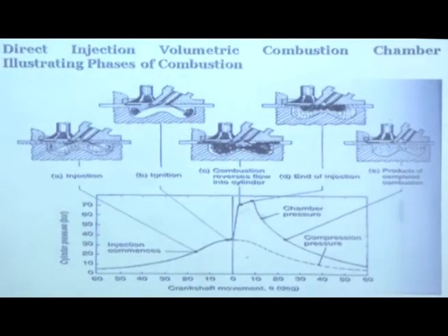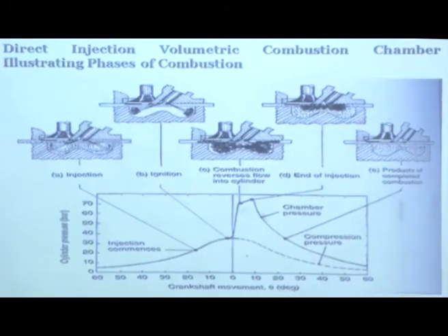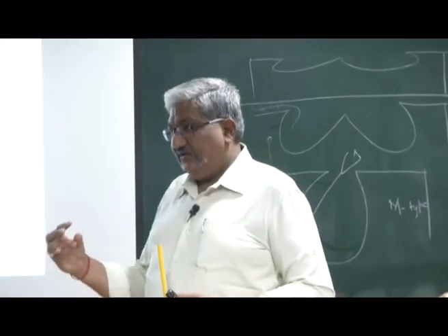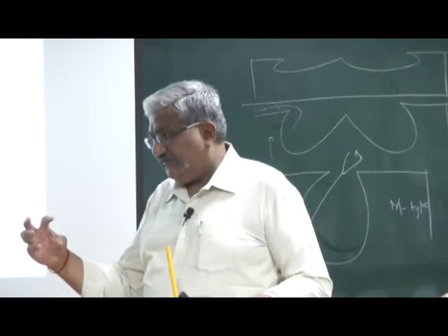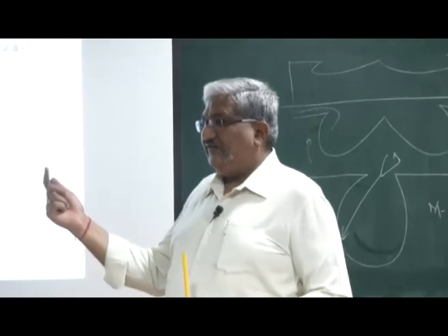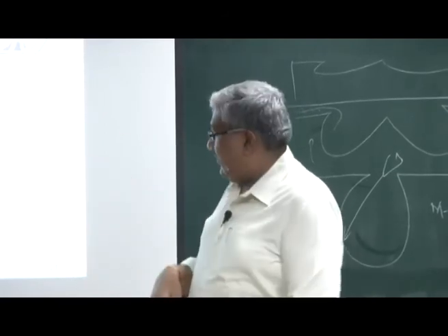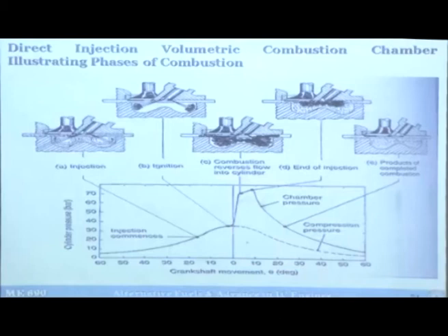Now, in an engine, when you want to study the combustion, the first thing that you do is look at the pressure crank angle history of the engine, and that gives you a fairly good idea of what is happening inside the combustion chamber. So in the cylinder head you put a piezoelectric pressure transducer, and on the crankshaft you put a high precision optical encoder. When the shaft rotates, for every 0.1 crank angle degree, it gives one signal, which triggers the piezoelectric pressure transducer and captures the pressure signal. Then you can obtain theta, the crank angle degree, and the cylinder pressure.